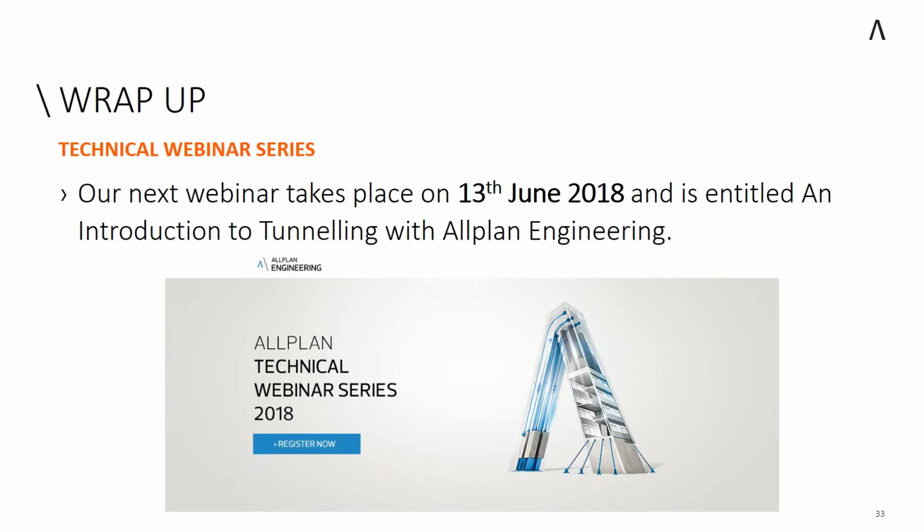Another question that's just come in, how can we import information into a DTM from a series of 3D splines instead of 3D points? Okay, right. The problem with a spline is that it is comprised of control points and other points that affect the degree of curvature or where that spline goes. If you imagine you are on site and you are taking levels across a field, say for instance, those levels form what is sometimes known as a string. If that string is a 3D line or a 3D polyline where the points are joined by straight lines, then we can read the vertices of that line and we can create points from it.